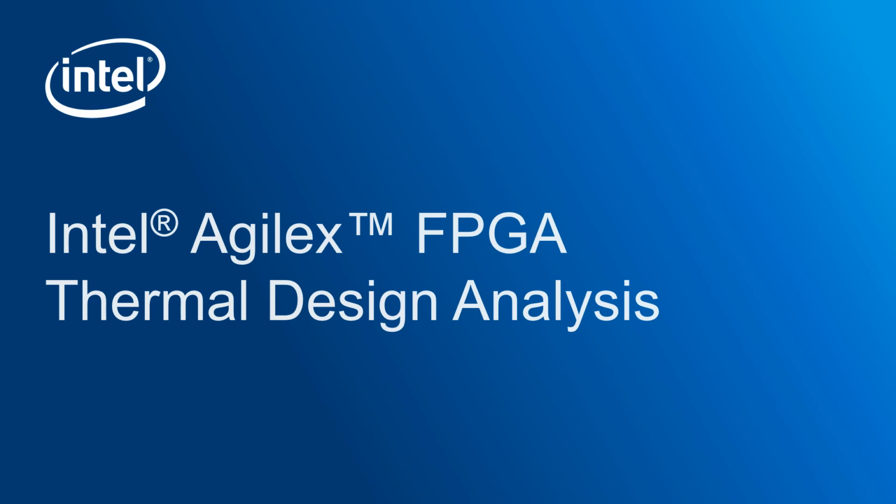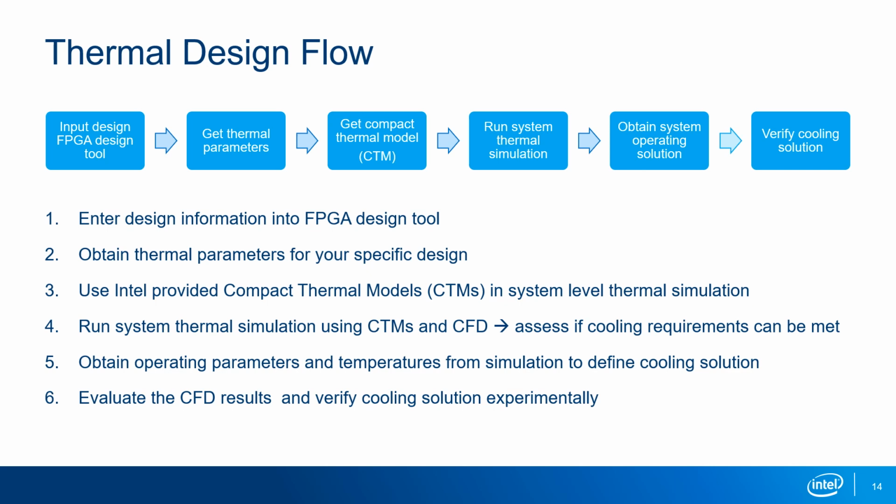Next, we'll talk about the thermal design analysis of your Agilex design. Here are the various steps to determining what kind of cooling solution will meet the requirements of your design. First, input your design into Intel's Quartus Prime software. The Power Thermal Calculator, the PTC, which we'll go more in depth later, and the Quartus Power Analyzer, the QPA, will estimate the power your design will consume. They will also estimate the thermal parameters of your design.